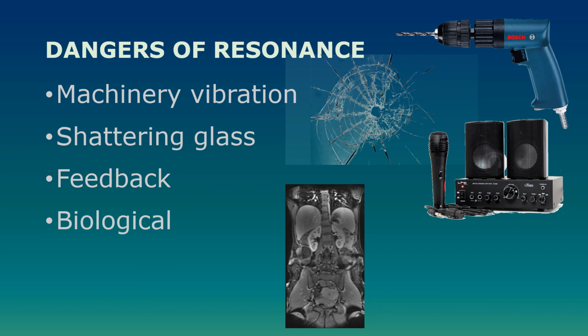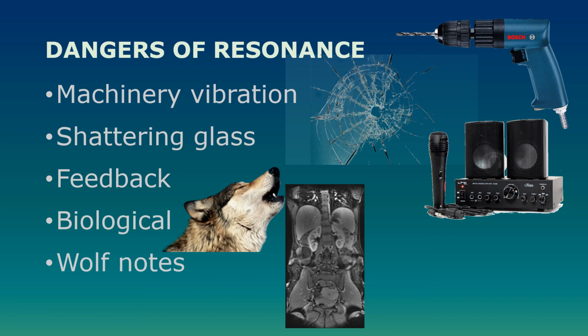Biological resonance can cause a bit of a problem. It links a little bit to the machinery one. This is something that has been recorded with people who work with heavy plant machinery quite a lot, where if the machinery is operating at a frequency that matches the natural frequency of, say, a body chamber, so the abdominal chamber, it can cause a great deal of discomfort as the internal organs, and the air or the fluids within them, vibrate with increasing amplitude, and it can cause some quite severe conditions and illnesses as a result of that. And obviously there are some hearing issues that would be related to that. So there's some phenomena there that need to be considered.